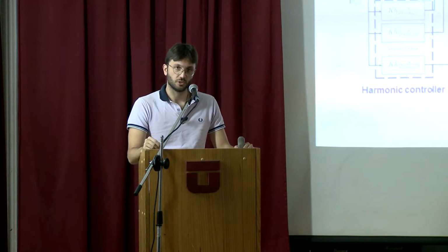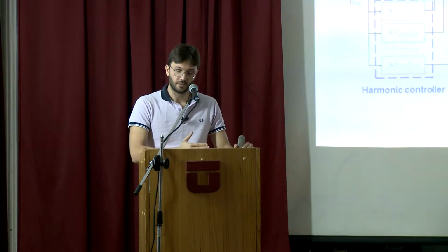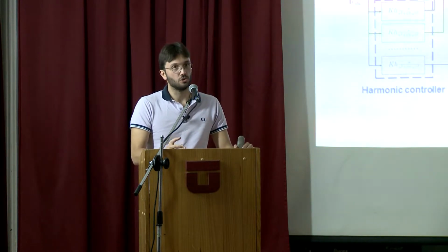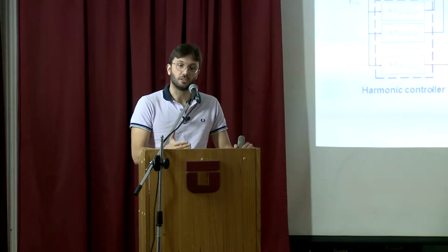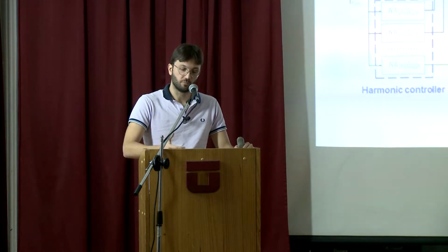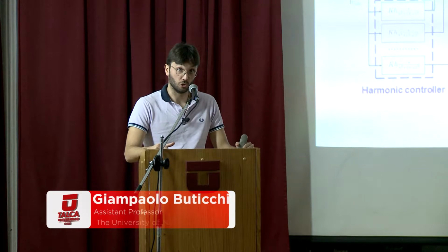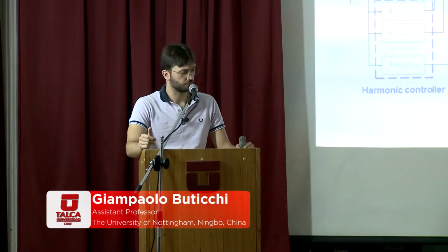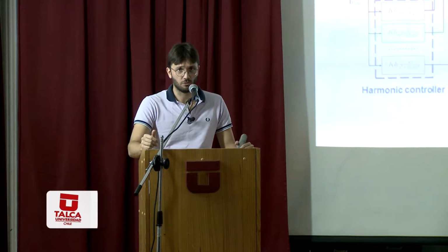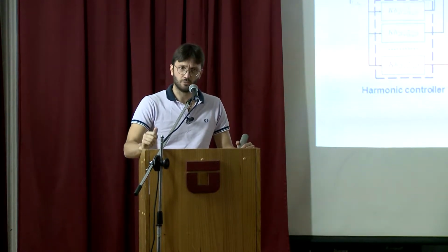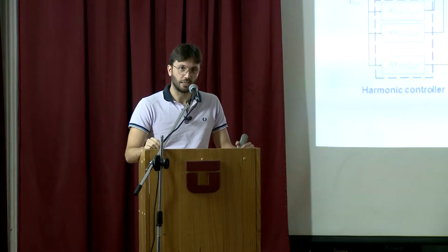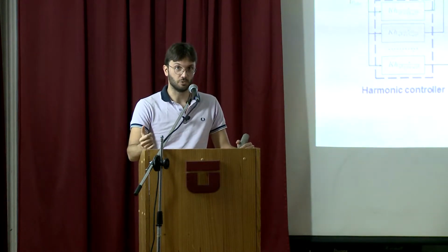So to make sure that the power supply is a nice sinusoidal waveform, you usually have to compensate for all the higher order harmonics, adding more and more resonant controllers at the different harmonics. So this was a possibility. Of course, not the only one. You can use predictive, you can use repetitive control, you can use many kinds of controllers to achieve the same objective.